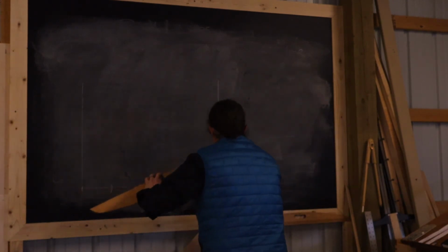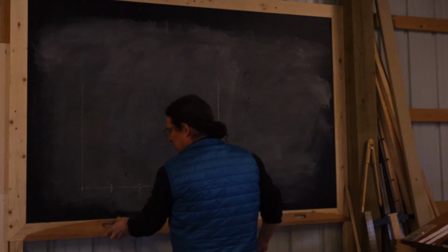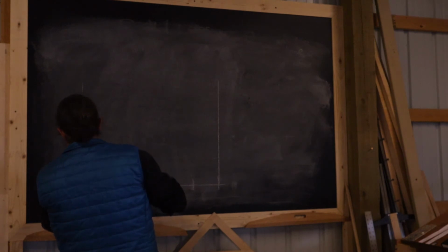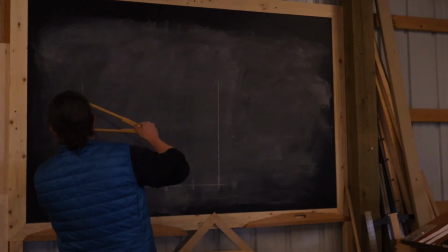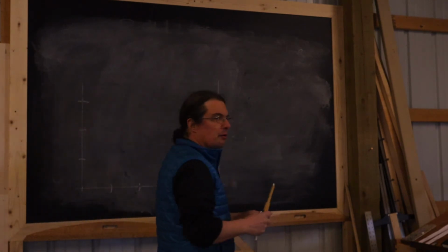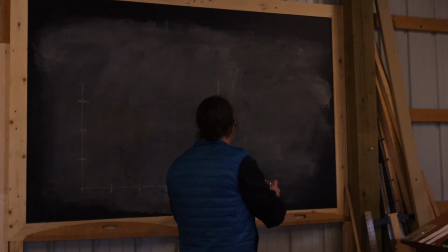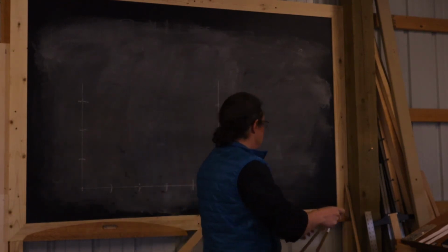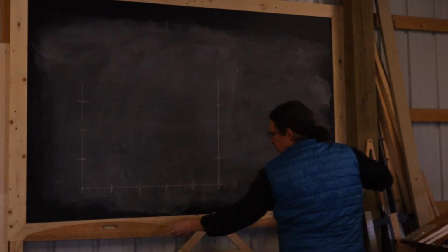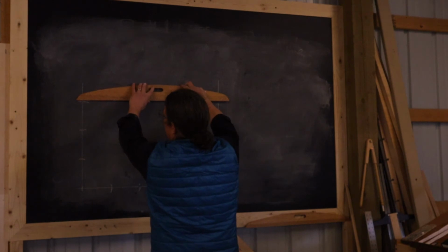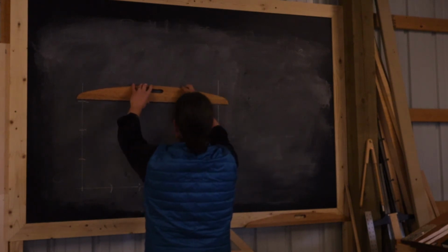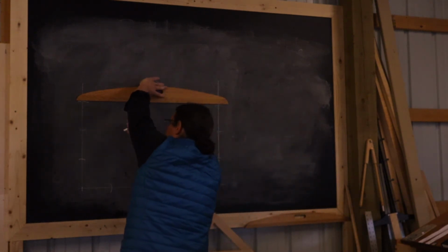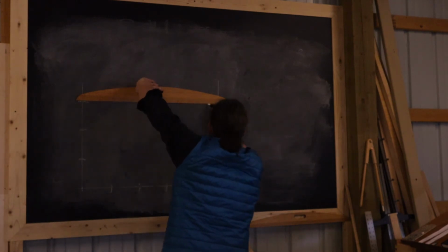Put the square away. Grab my dividers again. Mark out my 3 steps for the height on both of these perpendicular verticals. And the last step that follows, line my straight edge up with both endpoints, and then connect them.